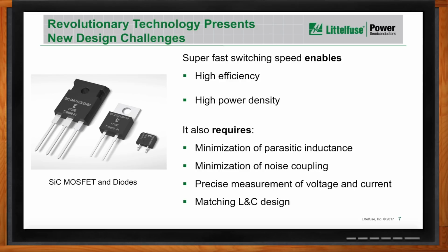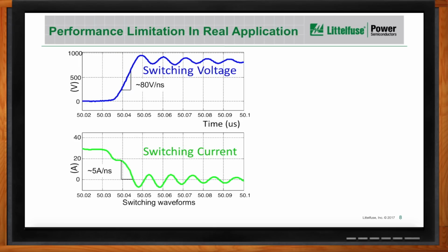Also, when you increase the switching frequency, you need to redesign your system not only for the power part, you also need to redesign all the passive components, your inductors, capacitors, and also your heat sinks, everything matching with the high switching frequency design when you're using carbide devices.